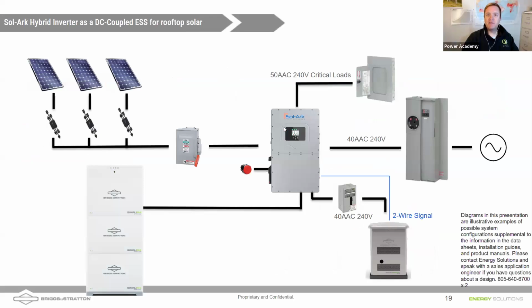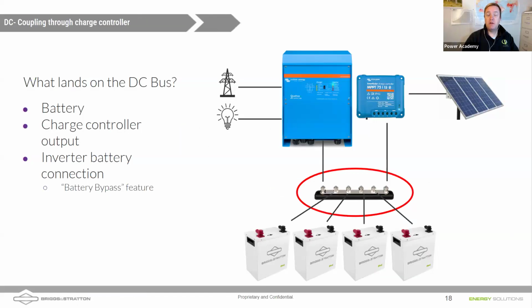One other thing on that charge controller there, Nathan, is it also has a load output. It has the ability to have DC coupled loads. I thought that would be kind of an interesting thing, and it can then turn off those loads just like that Morningstar could when the batteries reach a certain percent state of charge or certain voltage. It can cut off DC coupled loads. Mm-hmm.